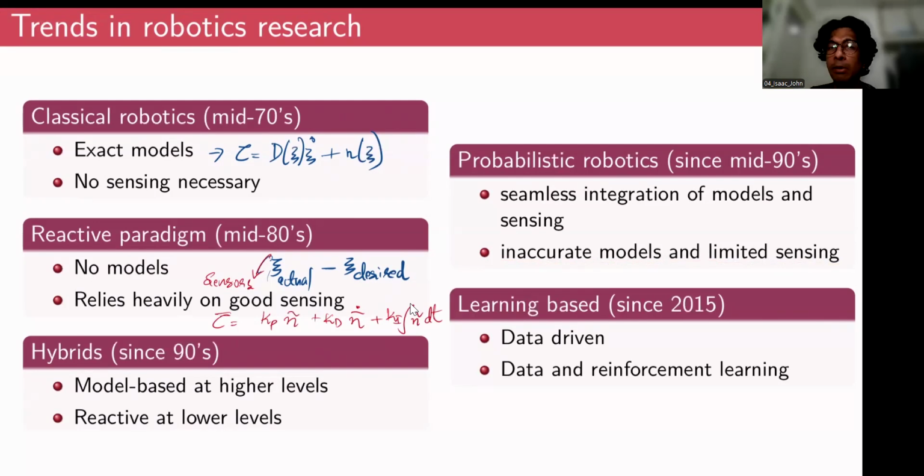So the probabilistic model acknowledges the fact that there are always going to be some inaccuracies or uncertainties in the robotic model. And whatever information we obtain from the sensors is also pretty much limited, because it will be riddled by noise, and the readings could also be influenced by the sensor characteristics.